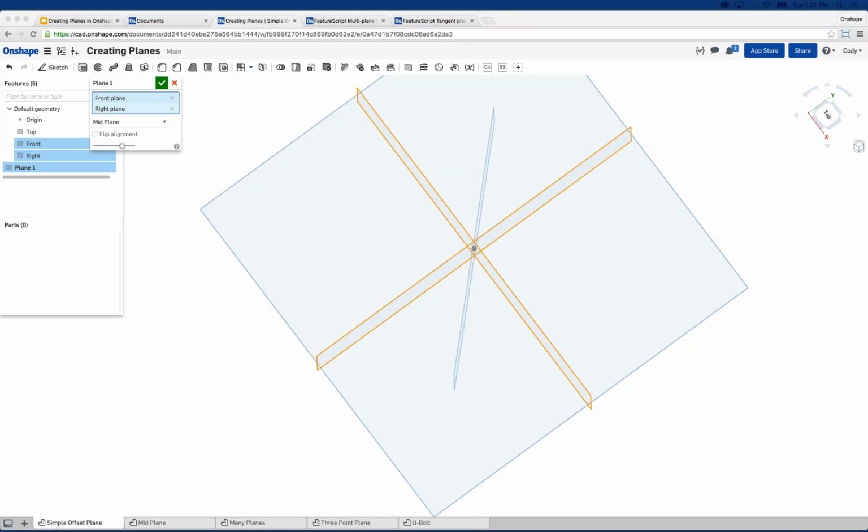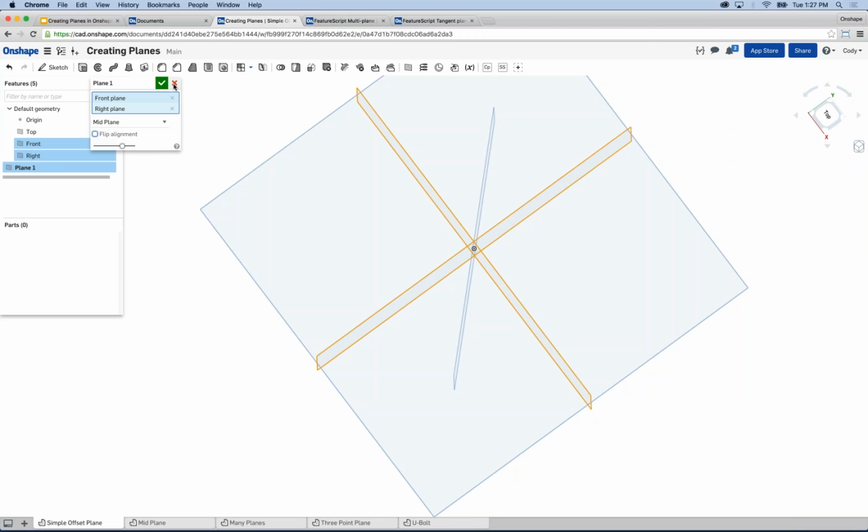Can you use a plane as an edge in a sketch? You can construct a plane using an edge in a sketch. Absolutely. I'm going to go over a curve point option, which allows you to construct a plane at the end of an edge, for example. Okay, so that is the mid-plane option inside the plane feature. One of the more common ones. Again, a very powerful one, and I think for many users, you won't need to do a line angle if all you're trying to do is find the center. Right? All right, so that is mid-plane.